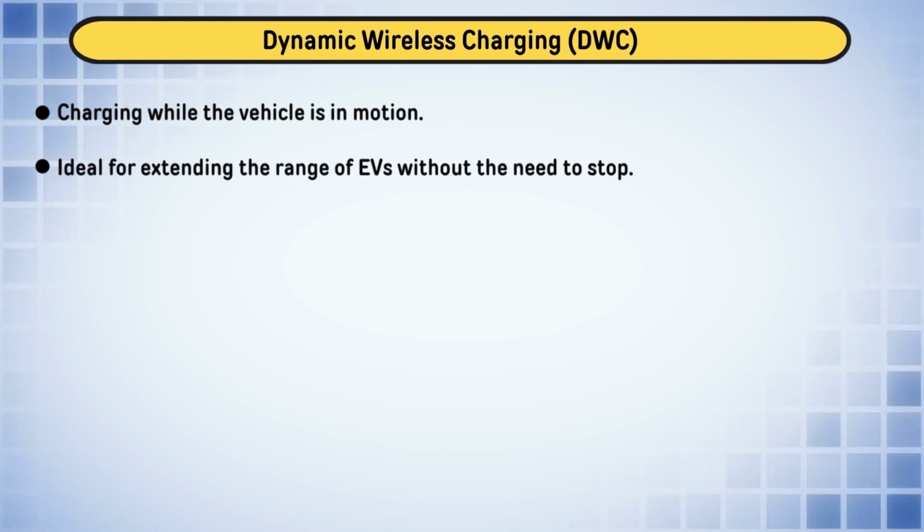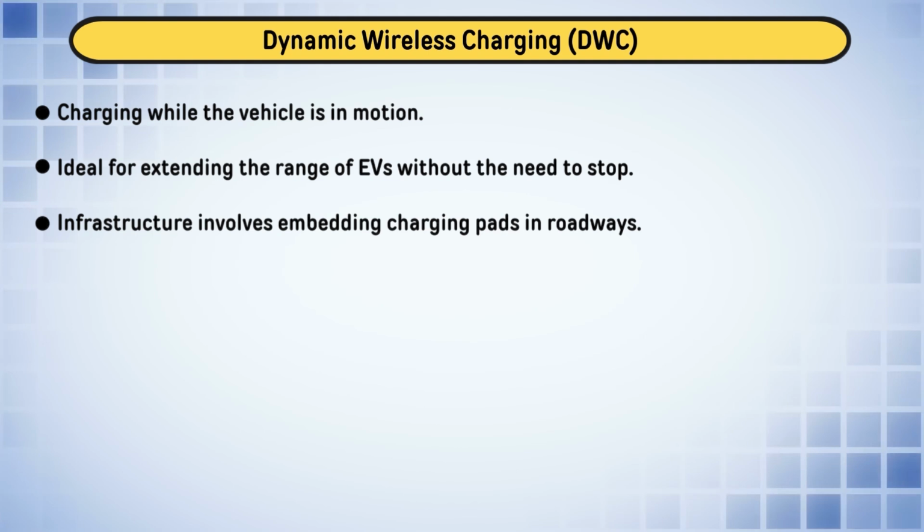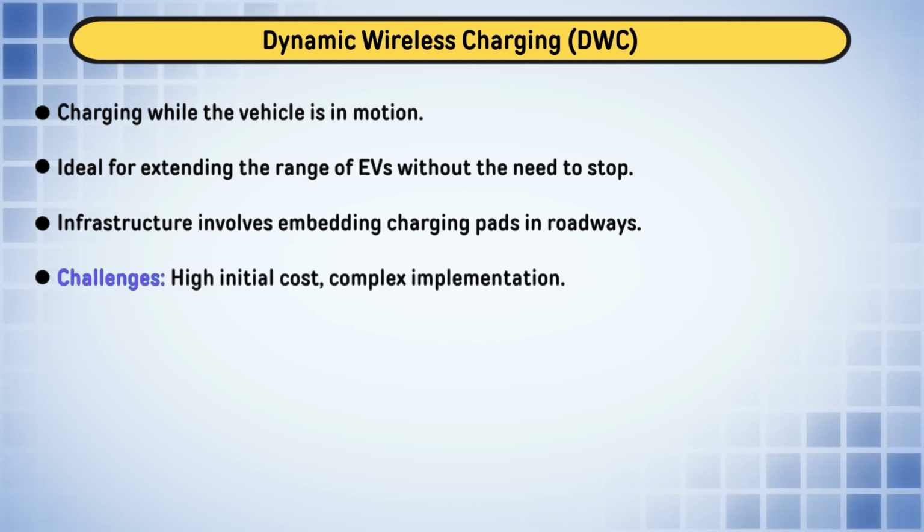It is a simple isolated converter, using one switch and one transformer. This is a high frequency transformer, it is not a 50 hertz transformer, because here the switch is on at a very high switching frequency, and for this high switching frequency we have designed this inductor.